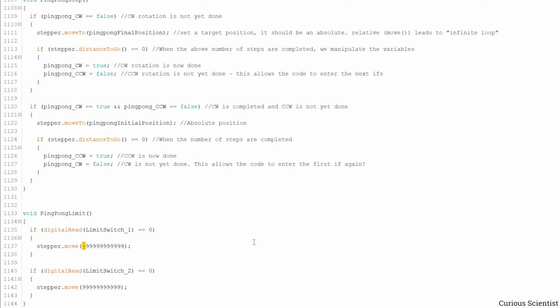And what is your positive and what is your negative direction, and what is your positive limit switch and negative limit switch when we are talking about the starting point and ending point of your linear carriage, for example. So then based on that, you have to select either 1 or 0, and you have to define these numbers either positive or negative. So then let's say we are moving in the positive direction. So then once after moving a lot, we hit the limit switch number 1. So then this becomes 0 and we enter this part.